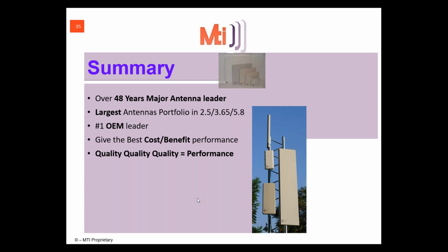Mostly it's adaptive, done by the radio. When you get a different kind of signal, the radio does the adaptation of the signal. There are two methods to do the combination between the antenna and the radio. Most people put the active component in the radio, and the antenna is a simple antenna, but it needs to support all the options. So mostly this is done by the software from the radio. And by the way, most of the radio vendors are doing this today, from Ruckus, Aruba, everyone.